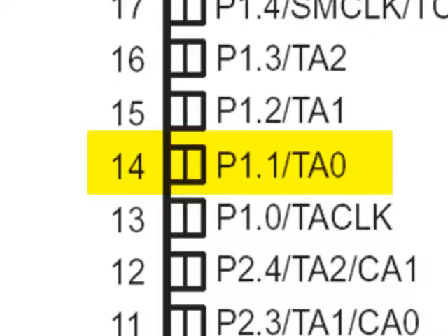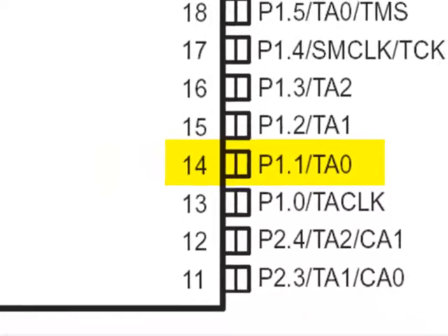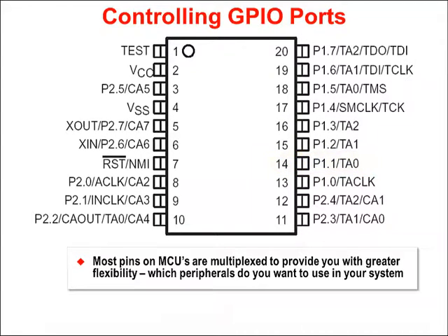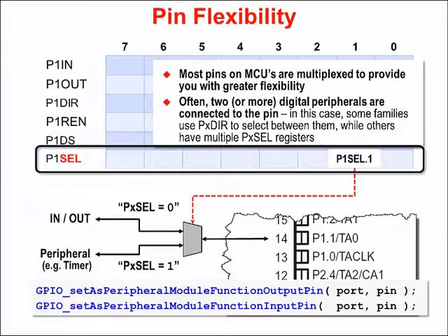Why do we do this? Well, we only have so many pins because, in the end, each pin costs money, not just on our devices, but on your board. Trying to be the most efficient we can, we allow multiple capabilities per pin. So that's where the term multiplexing comes in. We multiplex multiple functions onto a single pin. So part of your hardware design and software design has to take that into account. How do we deal with this?